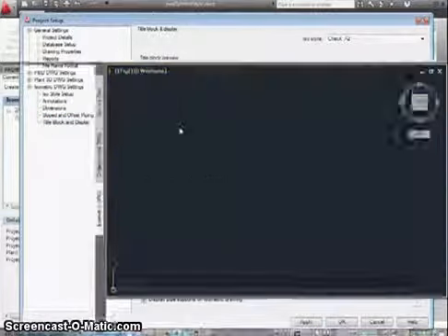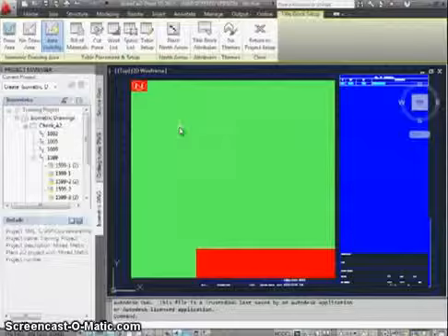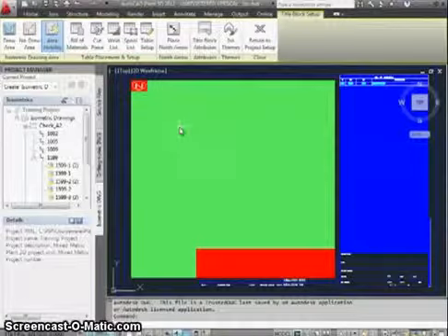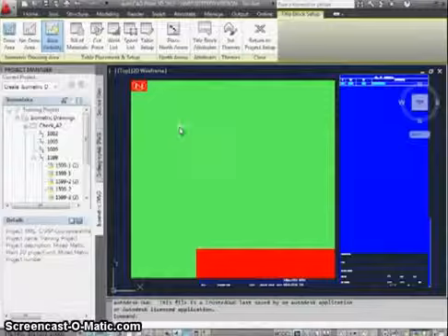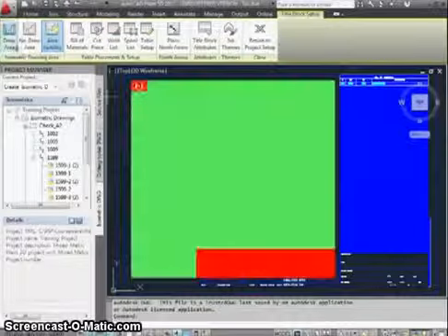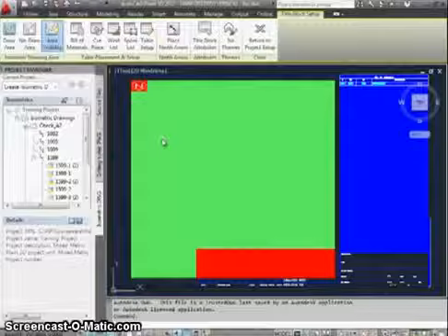Each ISO style has its own title block. We're going to modify these now in the title block setup. The large green area here is the draw area. It specifies where the ISO objects can be created. In title block setup, it's represented by a hatch that you can edit.